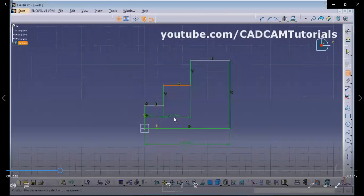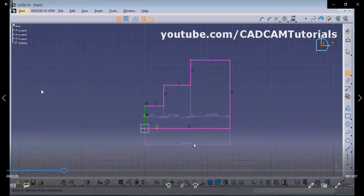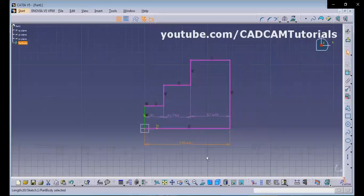Observe. Double click and give the dimension. Now it became over constrained because we have given this length also. So we will just delete this length. For that we will have to cancel it, select and delete. Then again double click and give the dimension. Click on this line, take your cursor to the left and click. Double click, again.